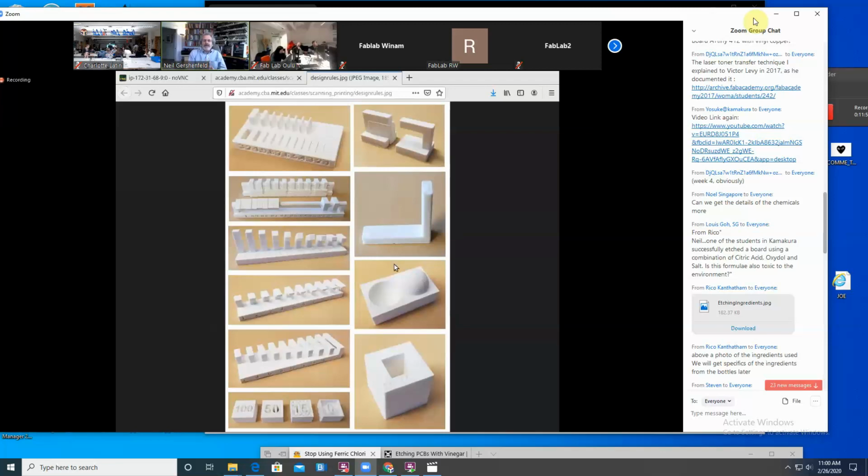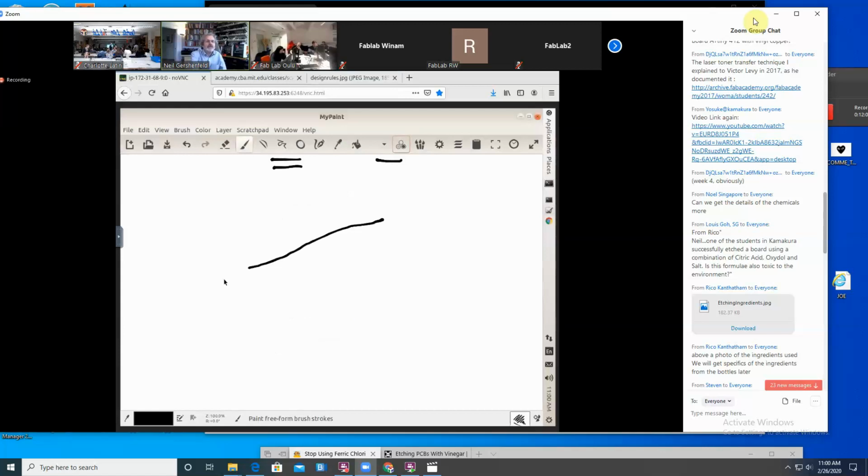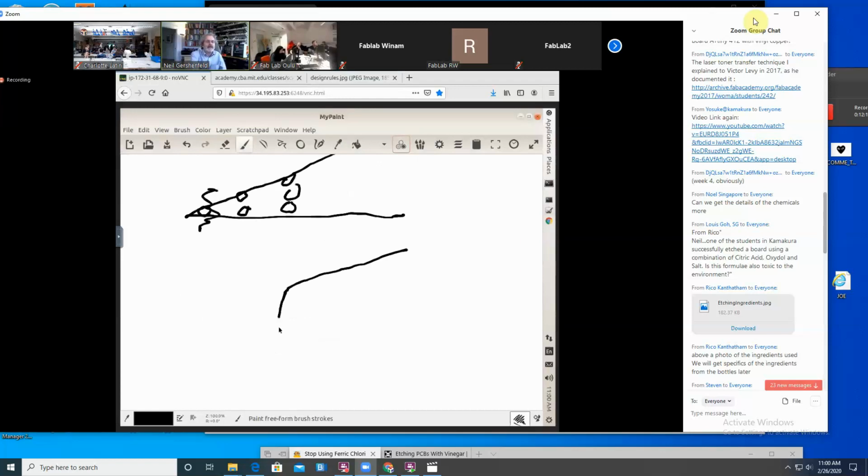So each of those are design rules, and they have many implications. So one example is you don't design a part with a sharp corner like that, because you'd have 3 filaments here and then 2 filaments here and only 1 filament here, and you'd get a tangled mess there. And so you want to design it with something like that, so there's a solid ending.